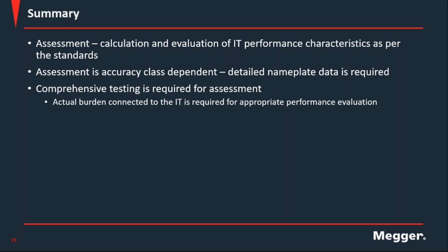And then you need comprehensive testing. You need to run all the tests that are recommended in the standard to be able to model that instrument transformer circuit, and also use the information from the actual burden to be able to assess and simulate the performance of the instrument transformer.